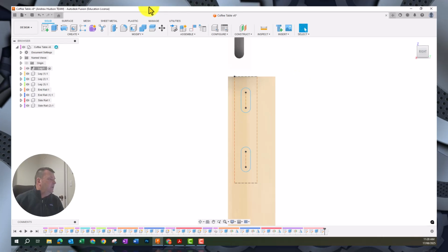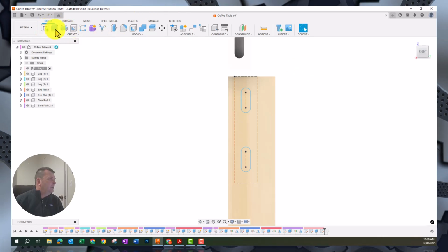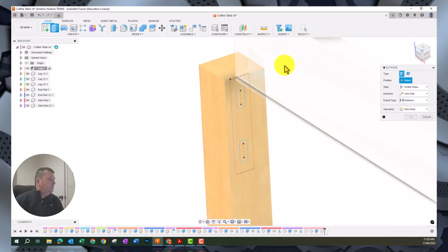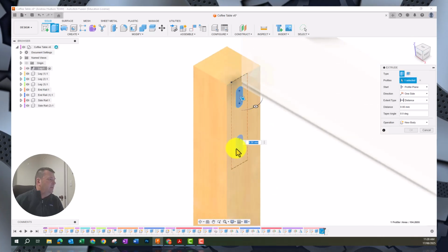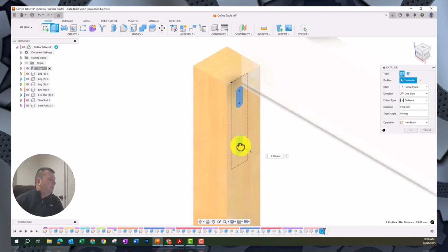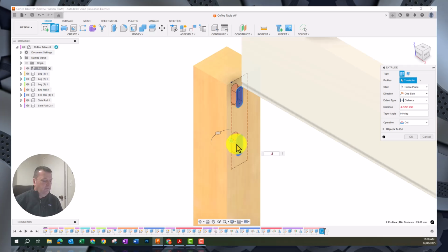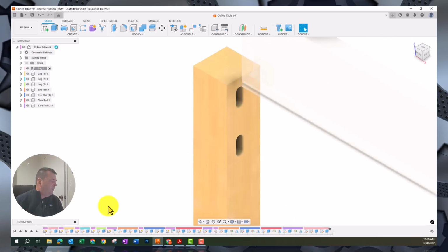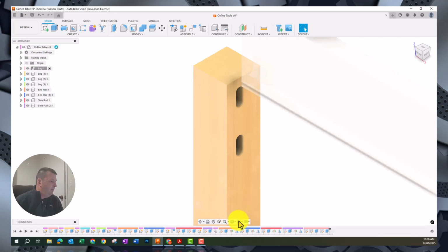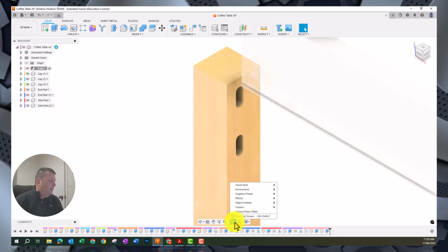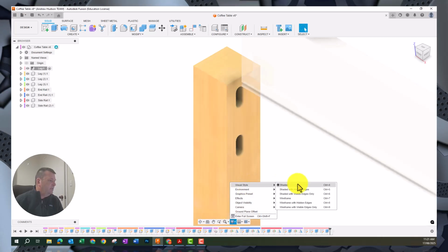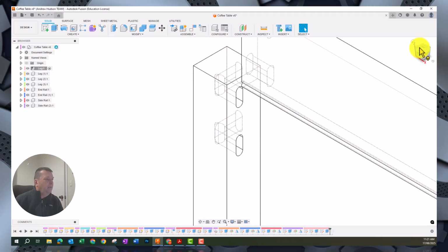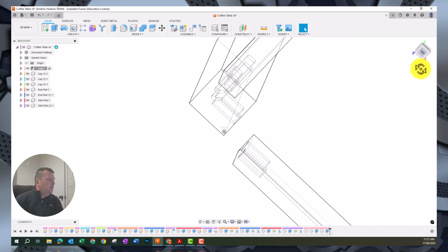Okay, finish sketch. And then we're going to punch them out. So we're going to go extrude. Spin this around a little bit. That one, and go back in. So we're going to go -25, enter. Okay, let's just do a quick view in a wireframe format and see whether they are interfering with us. So if we go to wireframes with hidden edges, okay, so you can see what's going to happen here.